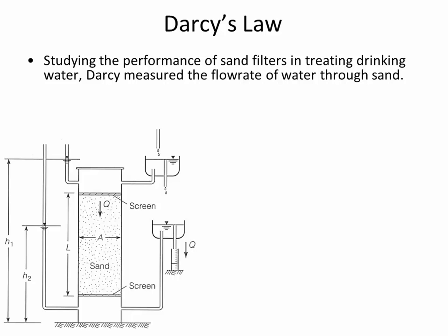They're these two different pools on the head end and the bottom end of the device. I think it makes a lot more sense if we show this device oriented sideways. This is the classic way of showing Darcy's law, but let me redraw it in a way that makes more sense to me. So here we've got, think of it as a big PVC, a plastic pipe that's full of soil, but we connect it to a reservoir, and here is the water. It's flowing this way, and then it's connected to a reservoir over here. The water level's not as high. So there's a difference in elevation here.